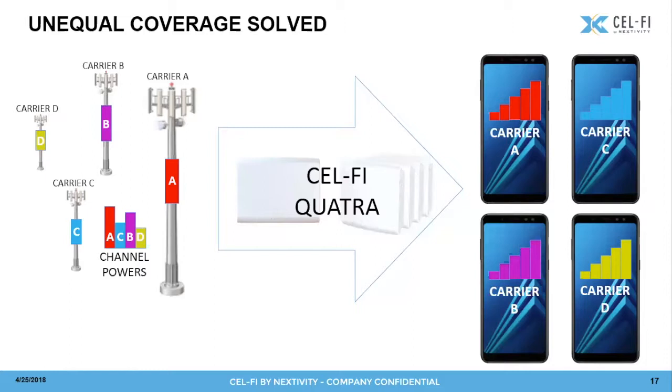You can do certain things with your phone, but it takes a lot of back and forth because it isn't something that those systems understand or can deal with natively. Quatra systems are connected to what's called the Wave Portal, and the Wave Portal gives you a wealth of information about the donor signals, about the gains and power levels. You can see everything happening in real time.